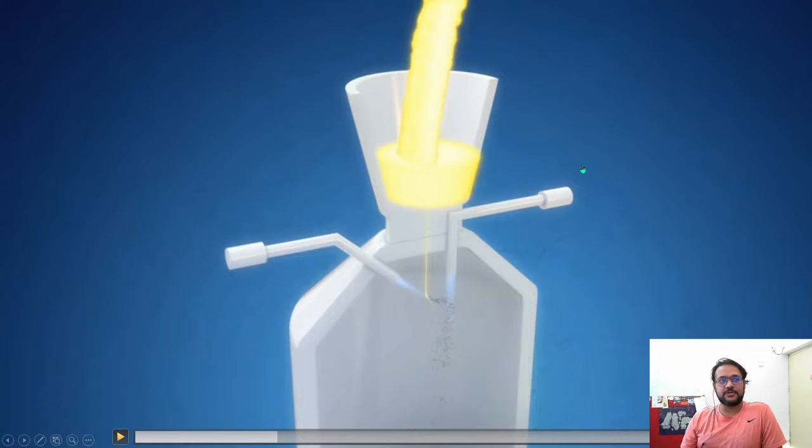So as you can see, the schematic that we showed in our images is something similar. You would pour molten material, and a thin stream of it is passed through at one point, and here they are using inert gases naturally, because inert gases would not oxidize the material. Otherwise, if this is steel, then it would rust, and the whole thing would not be suitable for use.